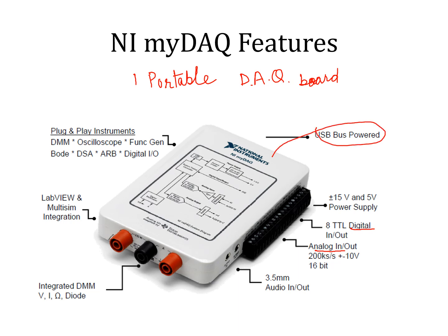We can even power it through the USB if we need only 5 volt, but if you want to give a higher voltage, you need to provide that through these power supply pins, that is plus minus 15 volts. Inside, the operational amplifiers will work only if you provide this much voltage from outside. So we have to provide an outside voltage like plus minus 15.